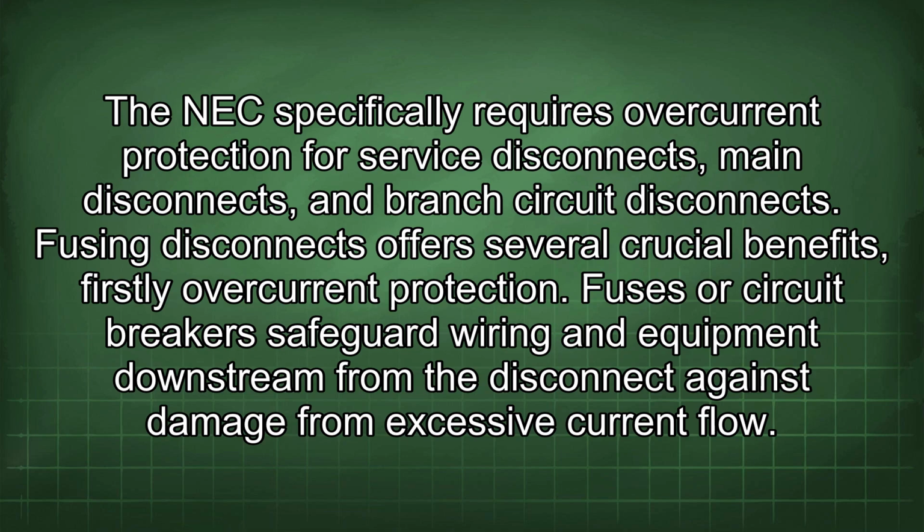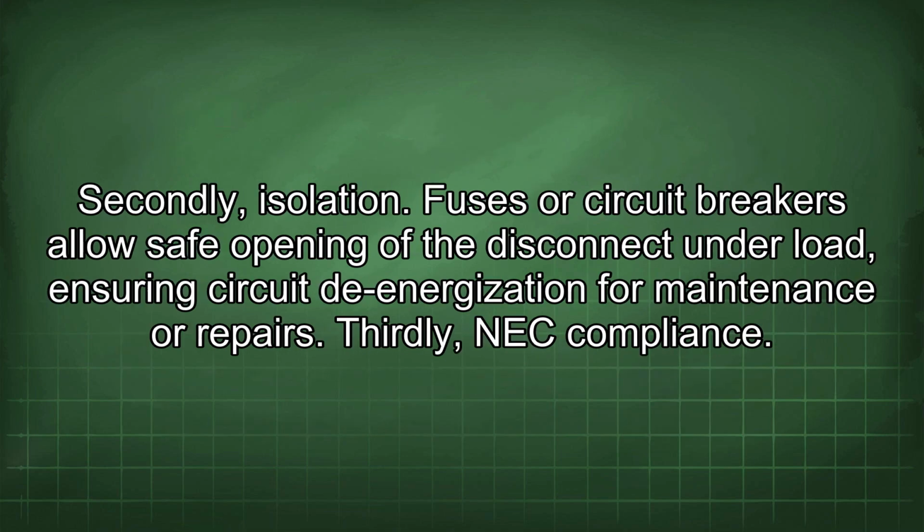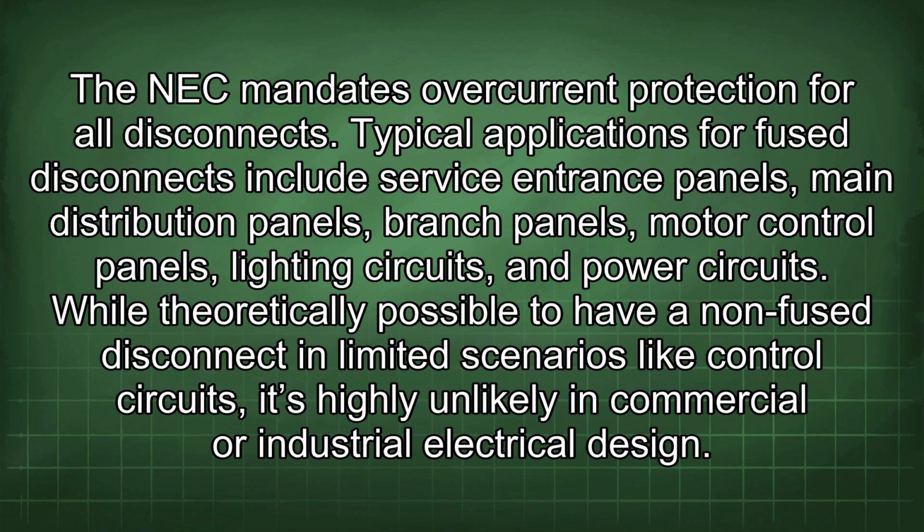Fusing disconnects offers several crucial benefits. Firstly, overcurrent protection. Fuses or circuit breakers safeguard wiring and equipment downstream from the disconnect against damage from excessive current flow. Secondly, isolation. Fuses or circuit breakers allow safe opening of the disconnect under load, ensuring circuit de-energization for maintenance or repairs. Thirdly, NEC compliance. The NEC mandates overcurrent protection for all disconnects.